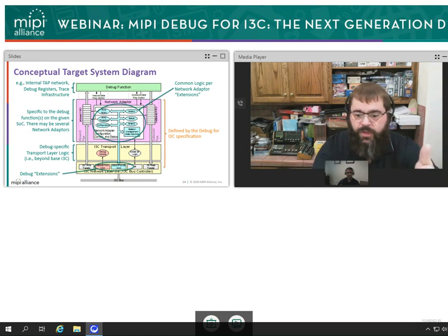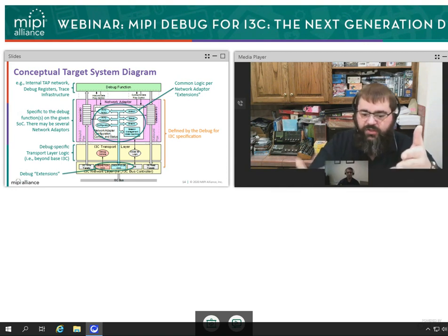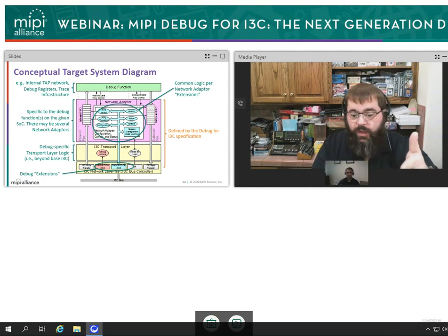For example, they could be optimized for different things: getting to an internal tap network, reading or writing different debug registers, consuming data as part of a read-only or an outbound-only implementation that deals with trace infrastructure. And depending on what you need for the debug functionality a chip needs, you could mix and match and include whatever needs to be included for whatever needs to be done.